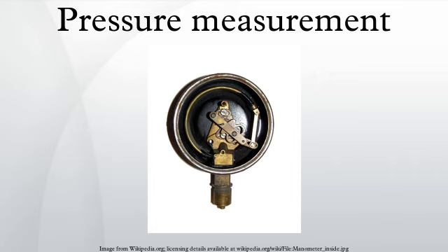Piston-type gauges counterbalance the pressure of a fluid with a spring or a solid weight, in which case it is known as a deadweight tester and may be used for calibration of other gauges. Liquid column. By using Bernoulli's principle and the derived pressure head equation, liquids can be used for instrumentation where gravity is present. Liquid column gauges consist of a vertical column of liquid in a tube that has ends which are exposed to different pressures. The column will rise or fall until its weight is in equilibrium with the pressure differential between the two ends of the tube.